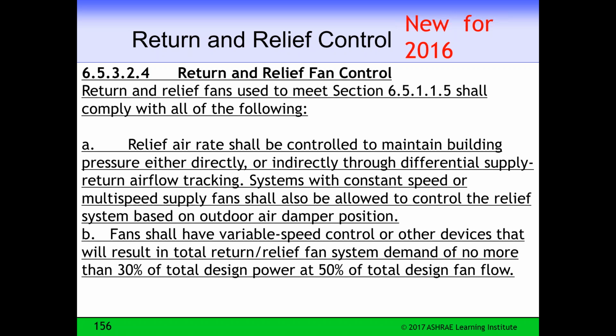So what we're saying is that you're going to put in a differential. Always when we're trying to pressurize a building, we'll have the supply fan supplying X CFM and the return fan returning X minus some number of CFM, because then the rest of the CFM is used to pressurize the building.